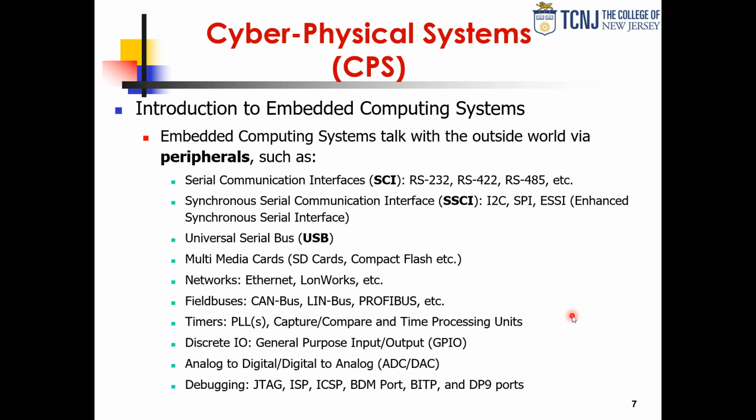The CAN bus has features of serial communications, but at the lowest layers, it still has a lot of safety features borrowed from avionics and fly-by-wire type of systems. So your anti-lock brakes, anything that has to do with safety in a car, your airbags, things like that are going to be on the CAN bus. Okay.